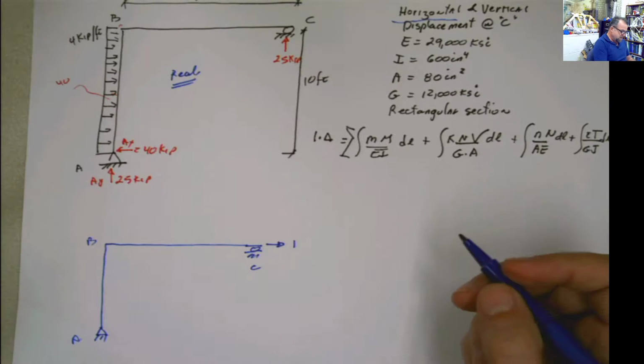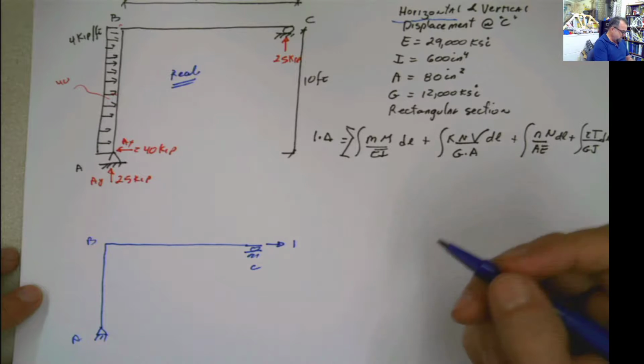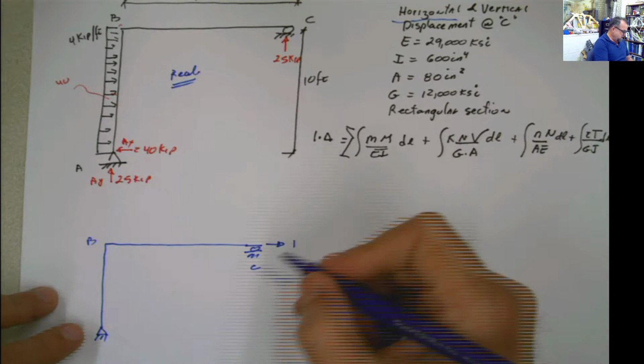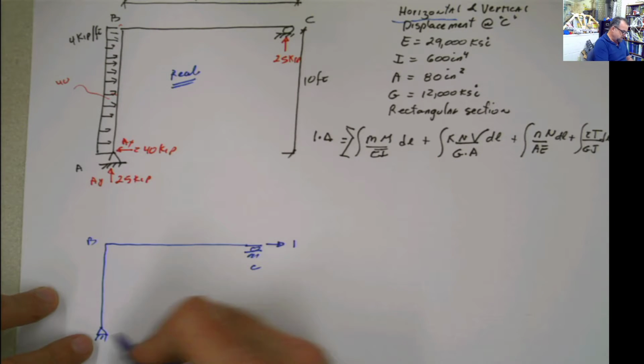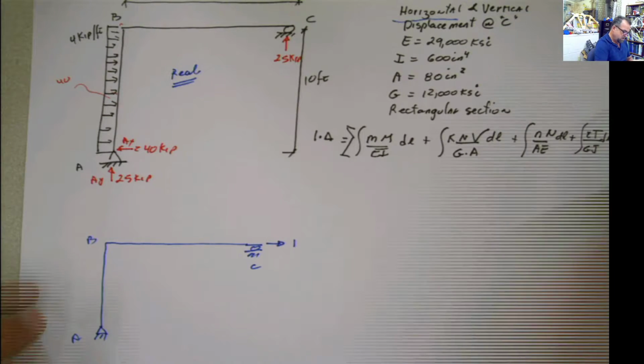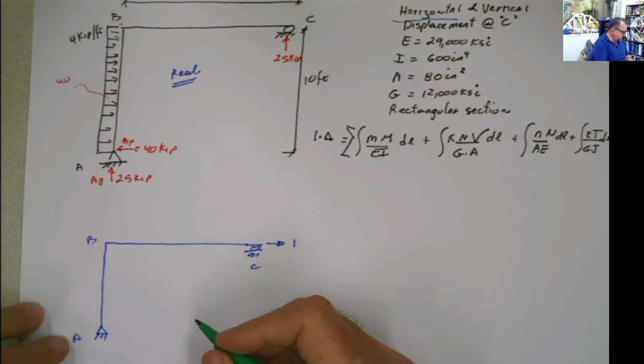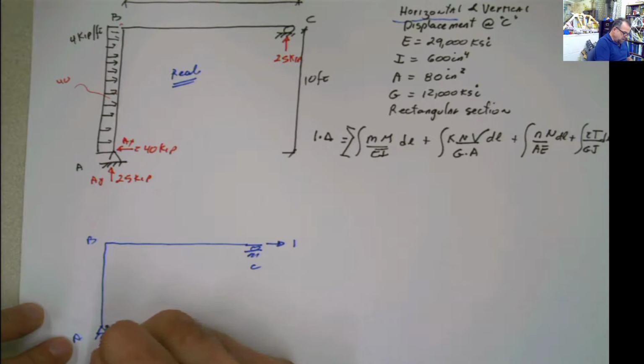And remember, I put 1, but that's 1 kip in reality. Now, what is the next step? The next step, as in the other case, is calculating the reactions. How much has to be the reaction here? Let me put it in green, because I barely use green. So this reaction here, if this is 1, is going to be 1 also in this direction, summation of forces in x.